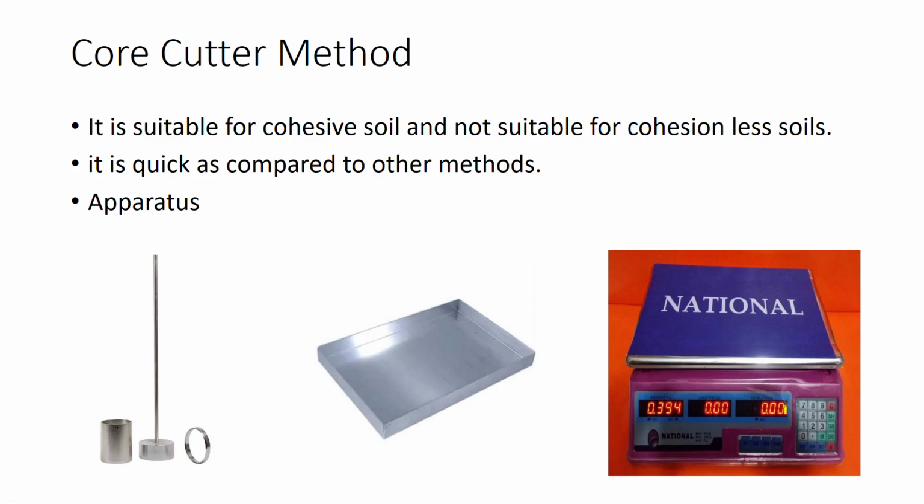Next method is the core cutter method. This method is most commonly used on cohesive soil and is not suitable for cohesionless soils. And it is quick as compared to other methods.